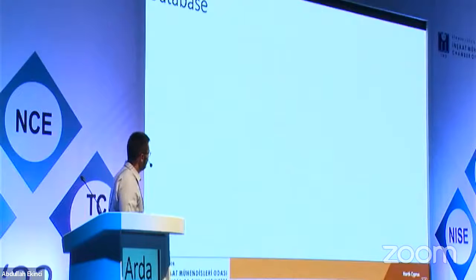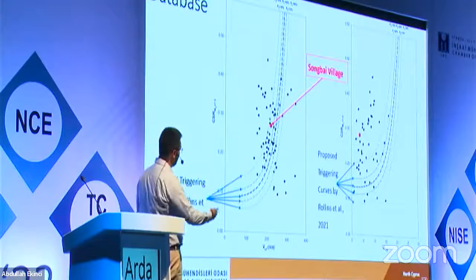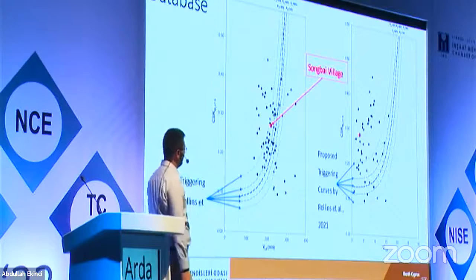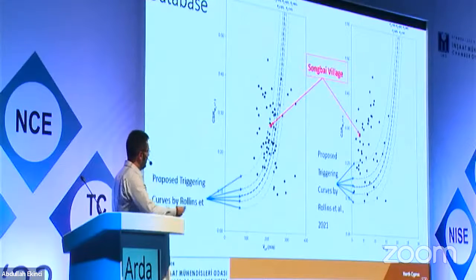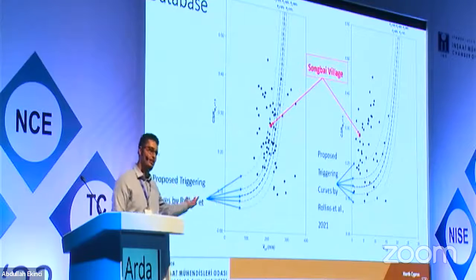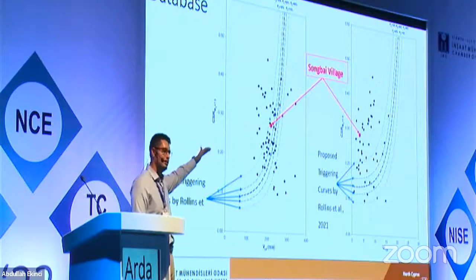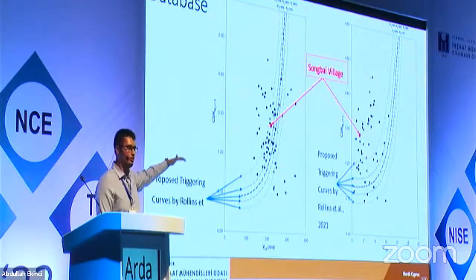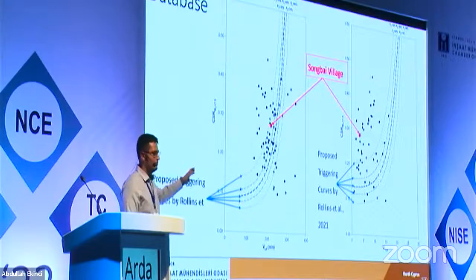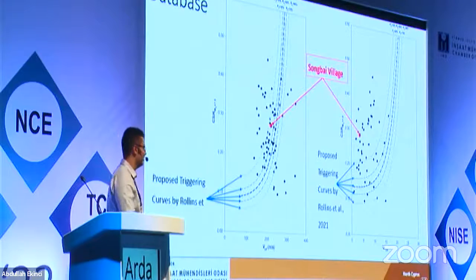By using these values and the triggering curves proposed by Rollins, I added all of my data for Wenchuan, China on these triggering curves. As you can observe from this, since most of these sites liquefied, DPT gives a better understanding since most of the data points here are on top of the 50% probability. However, in the VS triggering curves, there might be an adjustment needed for these curves.